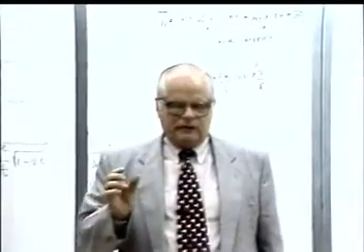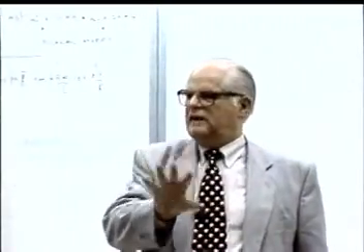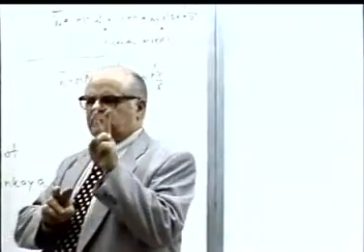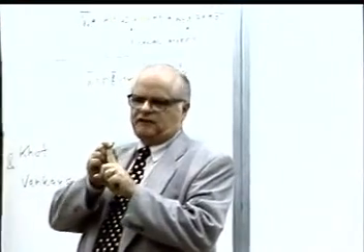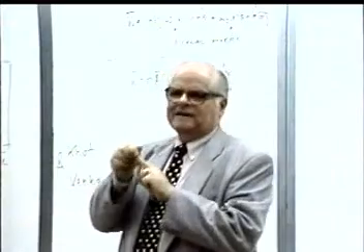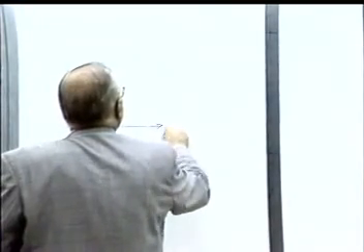The question was, there are people who say that composite shells are less imperfection sensitive than metallic shells. Essentially, the effect of imperfections consists of 2 things. One is the shape of the imperfection, B factor, etc. And then how big is it? Because you have seen these curves where for a certain shape, here is its amplitude.